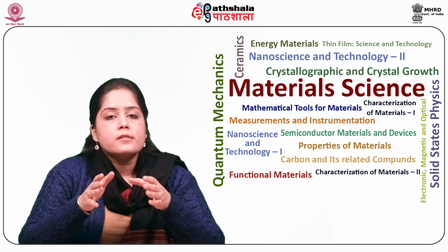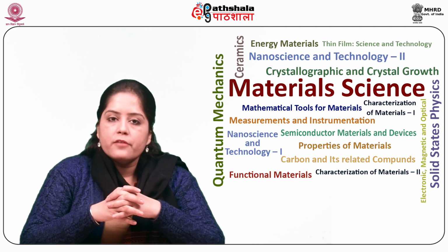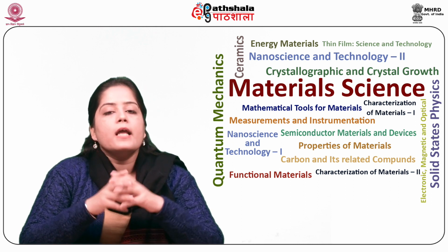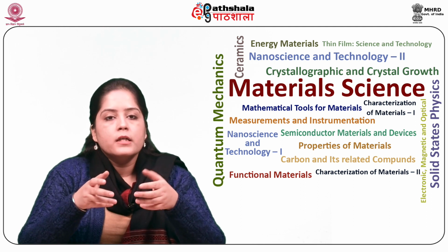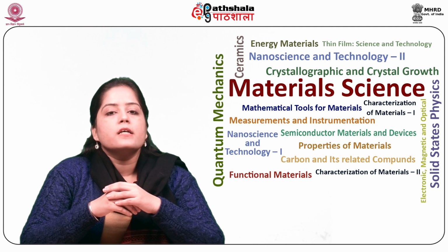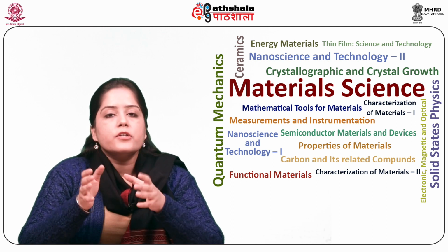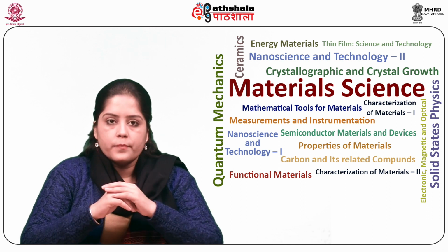So the changes in surface potential control the chem-FET device in an identical manner to the gate voltage, resulting in a detectable and measurable change in the conduction of the device.